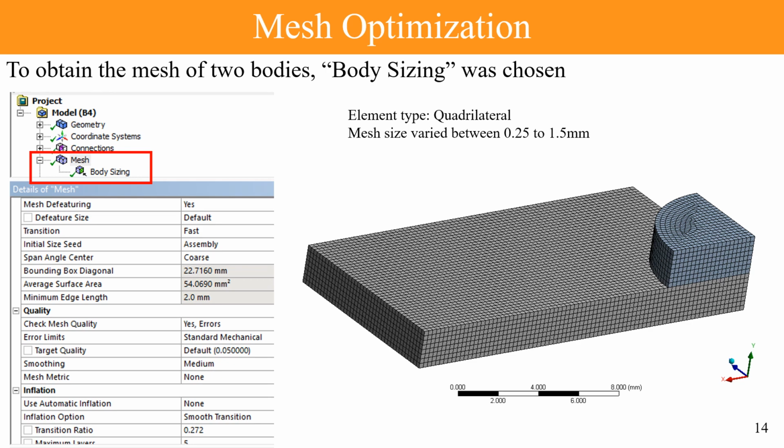First of all I put 1.5, and I tried to calculate the number of nodes, number of elements, and then I gradually reduced the mesh size. And just to let you know that the thickness of this substrate material on the tip is 2 millimeters, so I cannot go more than that, right? So yes, I did the meshing. I varied the mesh size from 1.5 to 0.25.